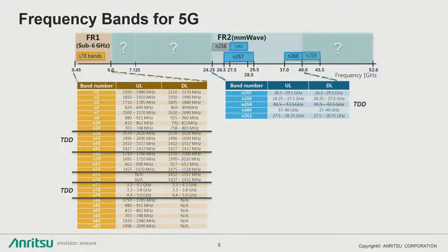There's a couple of reasons for that, but everything right now is TDD, right? So all of your 5G, whether it's FR1, which is sub 6, and it's funny we say sub 6 because the specification actually goes up to 7.1, right? So if you have an instrument that covers the entire band, you're good, right? No matter where you deploy 5G, you're going to be covered.